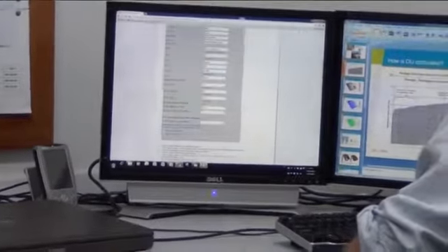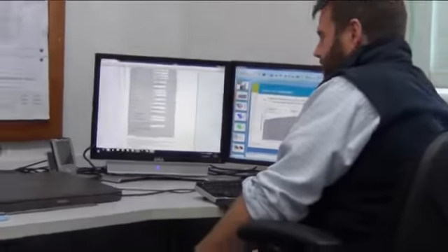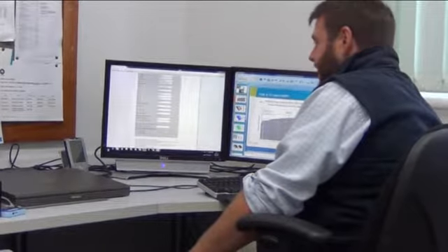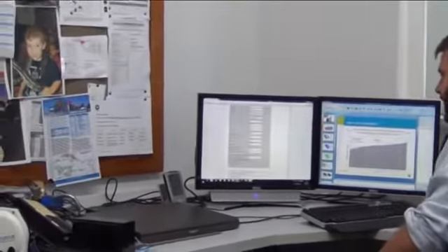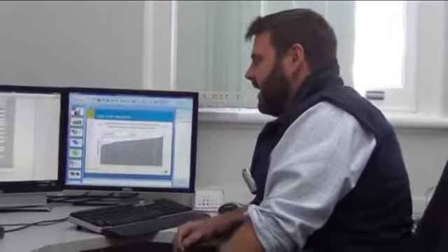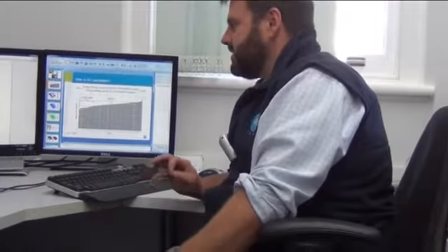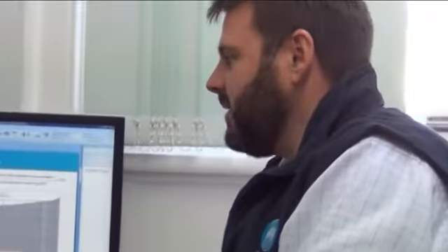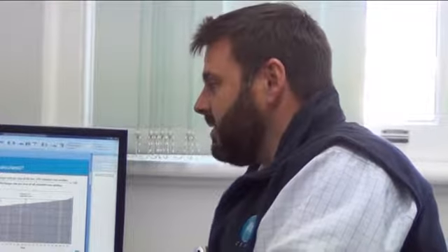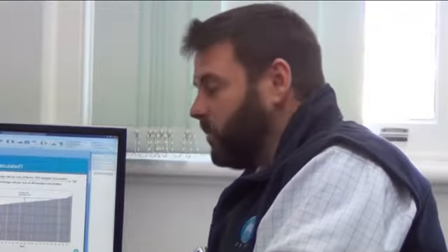That information is then used with the measured water application which we've done, and we'll create a variable map of what's actually been applied through your fertigation in terms of the nitrogen. The seasonal water use is most interesting. What it does is uses the information but works out how long you've actually run your irrigation system for over the season, and then creates a total water applied over the irrigation season in megalitres per hectare. So you can really have a look at the difference in water applied across a particular vineyard block.